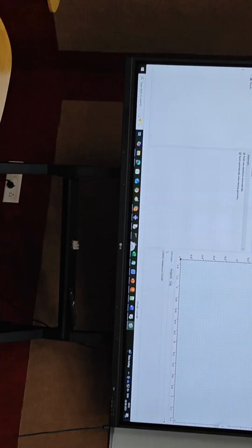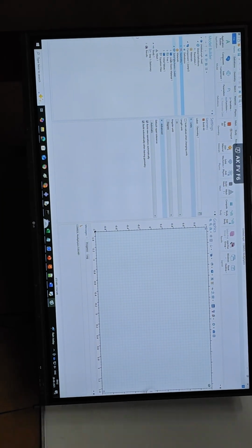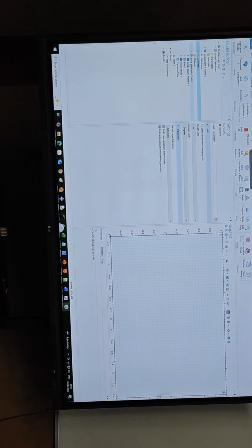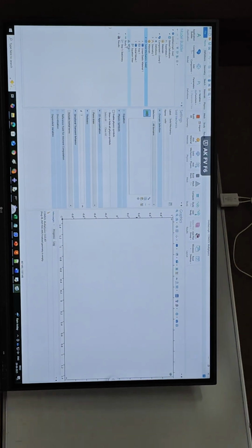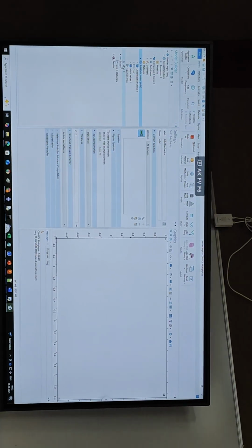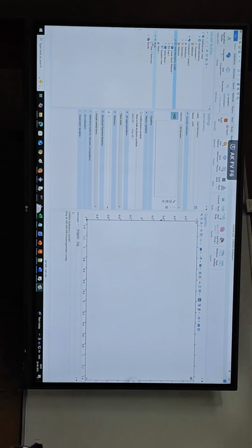Here, solid mechanics was added first, so solid mechanics will appear first. Now if you add another module, there are combined modules, like heat transfer in solids and a few others like Joule heating. Joule heating is a coupled physics where automatically you'll get 3-4 modules. They'll come in an order. This is where you'll have the physics falling in order. After that you'll have your mesh. That is where you'll mesh it depending upon the type of custom mesh you want. And finally, because we added the study earlier, we have the study here.